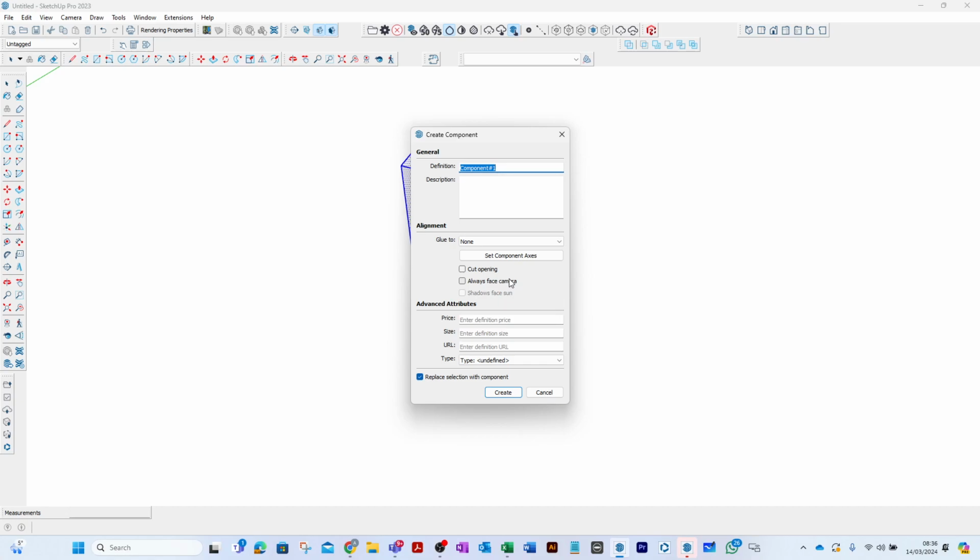So we need to give this definition a name. So what we'll do is we'll go 2 for the level, which is the structures. We'll then go ZZ, because it's not defined to any level yet, any ground floor, first floor level yet. And we'll then go stud, PFSTUD. Make sure you get the capitalization correct in the same way how it's written in the spreadsheet.